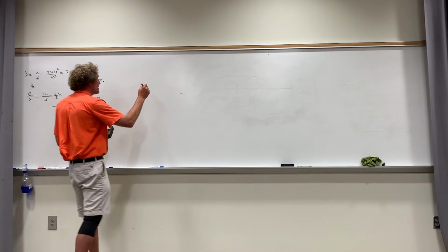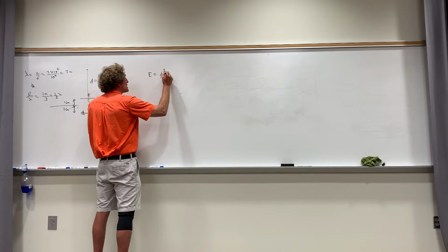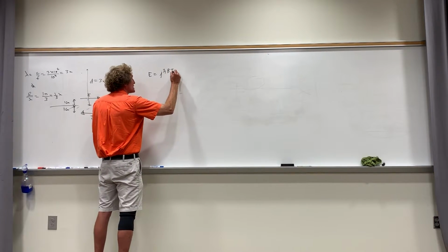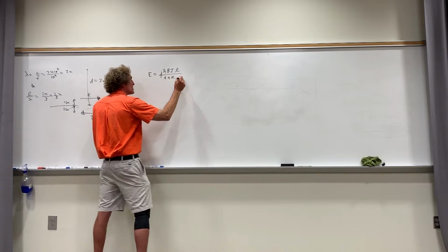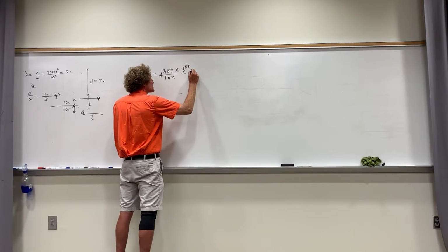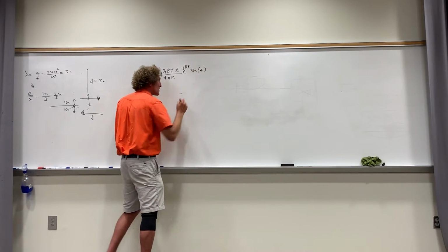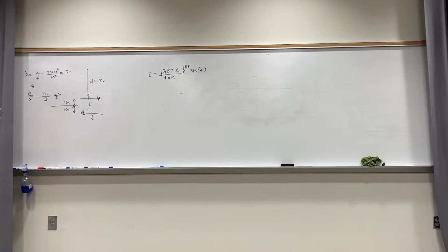So now I know the E field for a short dipole is j eta beta I times the length of the dipole, all over 4 pi r, times e to the minus j beta r, times the sine of theta. Correct, class? That's for a short dipole. I only care about the magnitude of the E field, don't I?